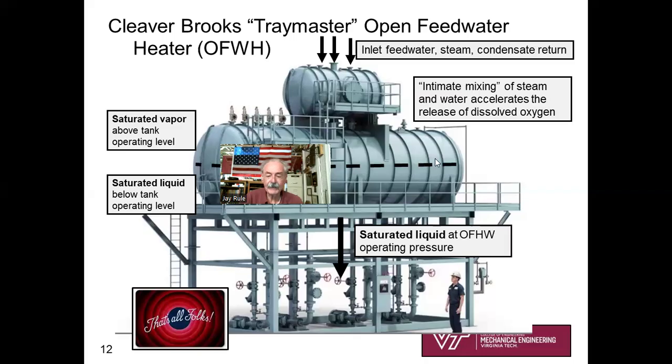Wow, so I blundered through that. So the beauty of this open feedwater heater is to get the water back up to the boiling point at that operating pressure of the heater, in order to remove dissolved oxygen, which really leads to terrible corrosion problems within the boiler. And another thing is just recognize that what's coming out of this tank is saturated liquid, just sort of by observation, saturated liquid.